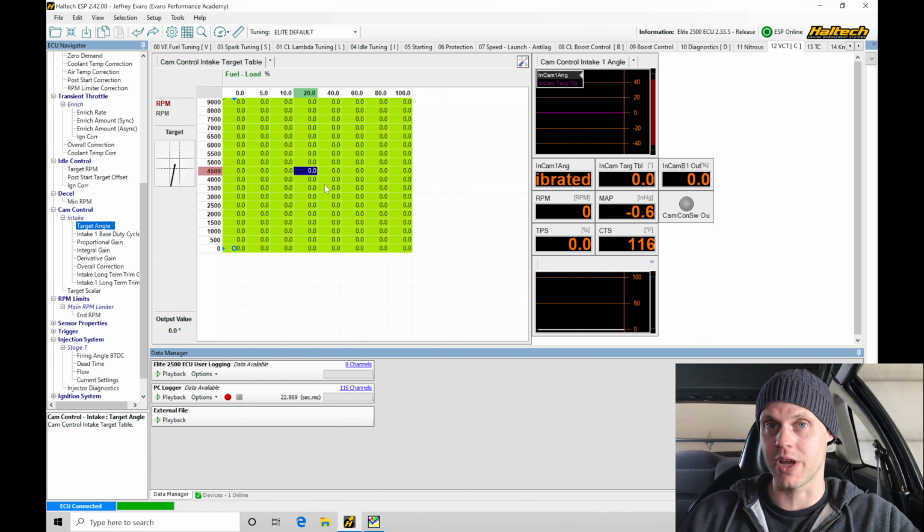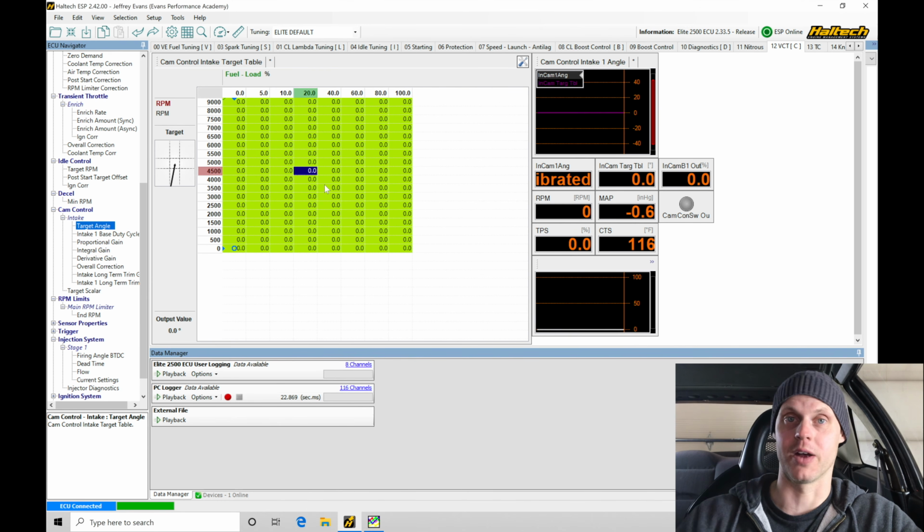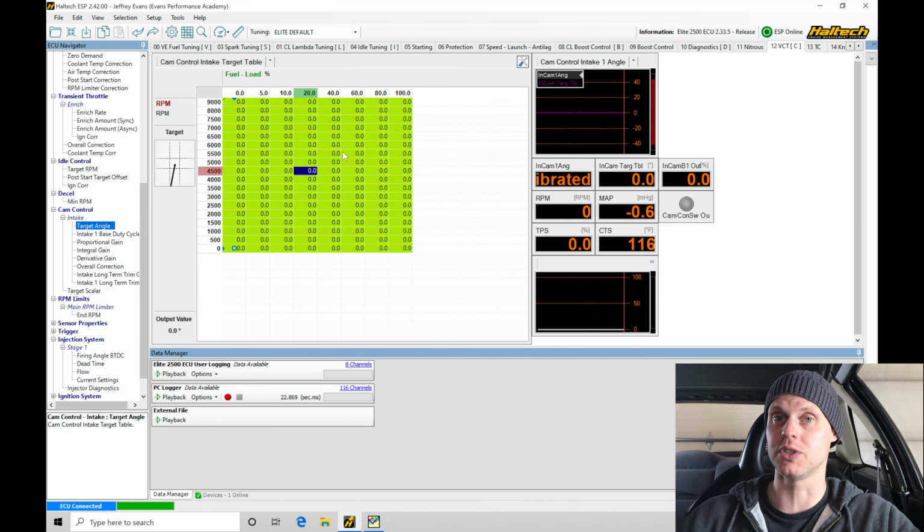Because the exhaust pressure increases, it's going to have a blowback effect. So if our intake pressure is at atmospheric, let's say, and our exhaust pressure is at 2 pounds or 3 pounds of exhaust pressure, if we're having too much overlap, that allows the exhaust pressure to push back into the combustion chamber rather than drawing out any of that burnt gas. That's going to actually have the opposite effect. We can lose power, so we need to rotate the cam back and have it go more towards the neutral position, which is 0. So our job here is going to be evaluating, making our cam target changes.